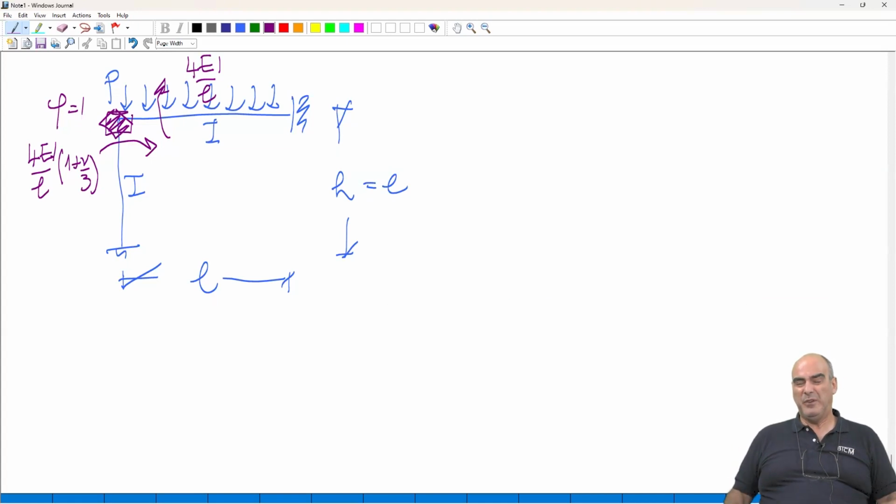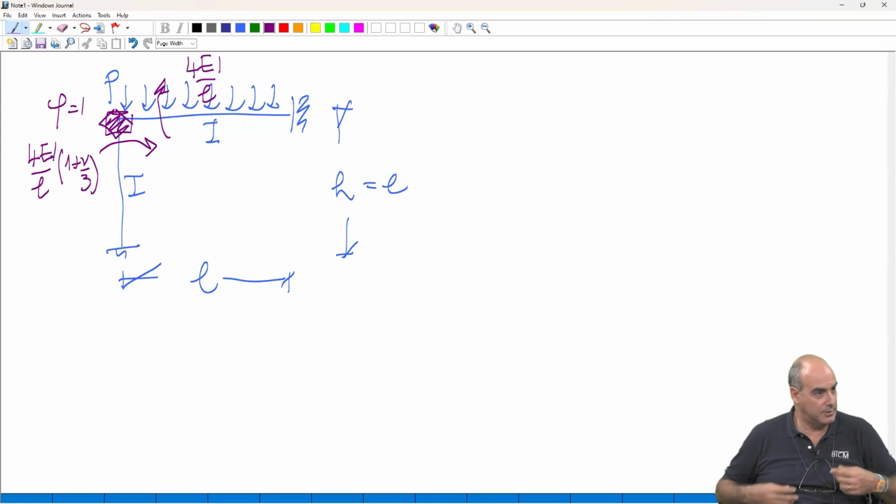But what axial force shall I expect in the beam? Yeah, it's the shear of the column which becomes axial force in the beam. But shear in columns is not so high and not so critical. So generally, especially if we have to solve by hand, we can make the simplifying assumption that, at least in the first step, we neglect the axial loads in the beams. So if we neglect the axial load, the correction function is 1 plus 0, which is 1. It's not there.